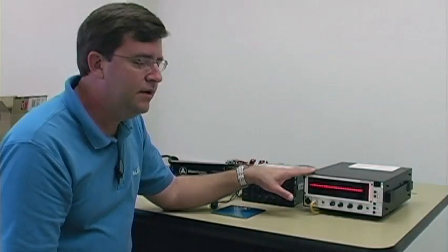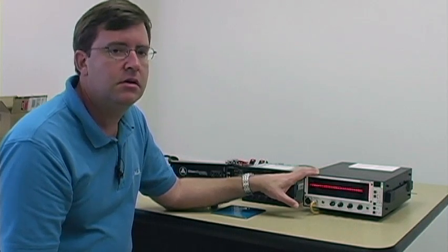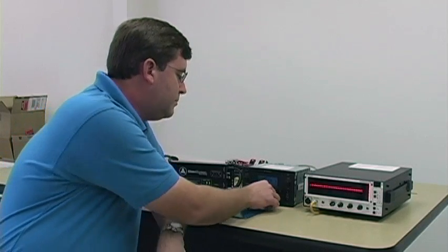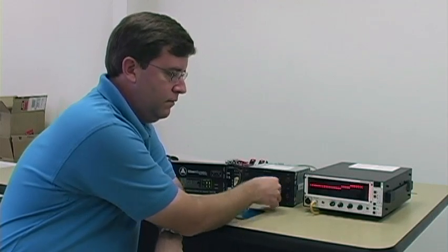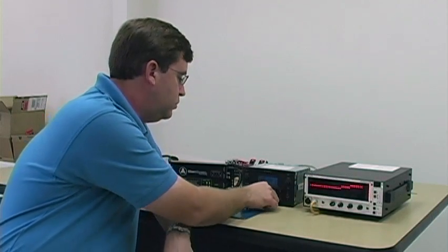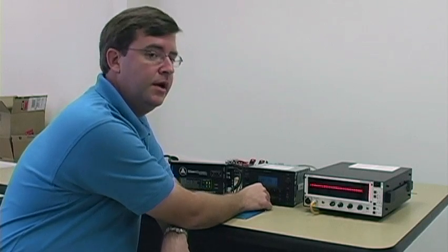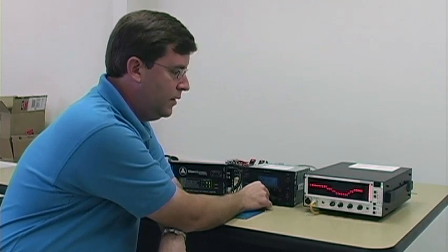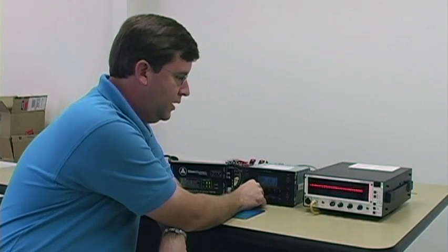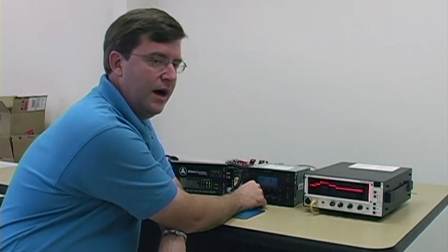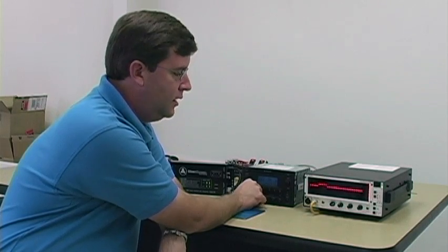Okay, now that you've achieved a successful calibration and you have a nice flat frequency response, you can still operate the head unit's tone controls and they will behave appropriately. Here's a nice treble boost. This one has a mid-range control, so we can apply a mid-range cut, for example, and you can see that that totally works just fine. Or a bass boost, a little bit high for our taste, but nevertheless the tone controls are fully functional.